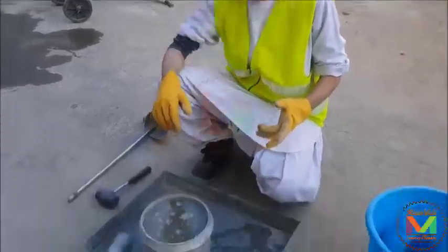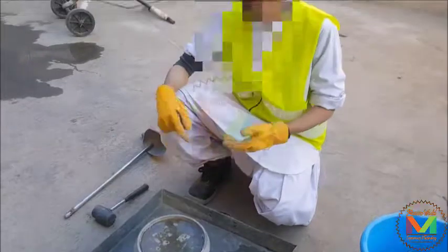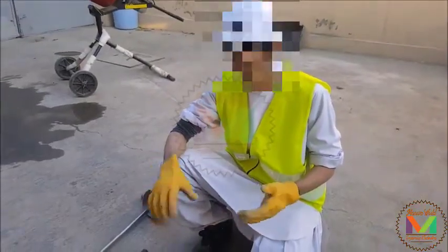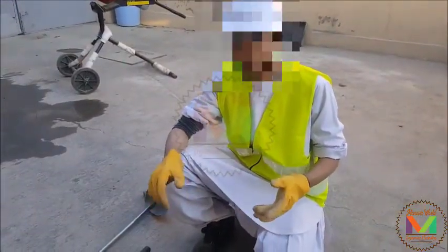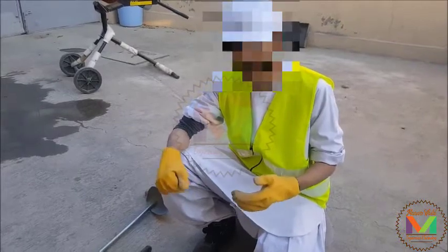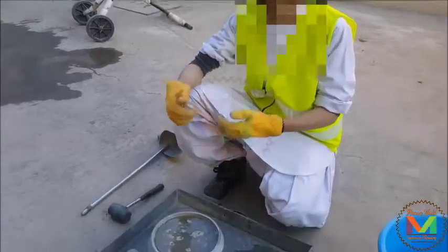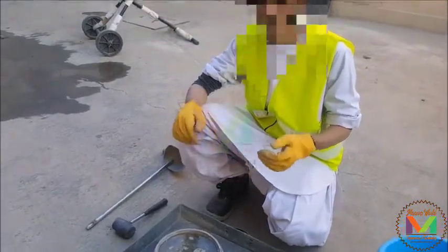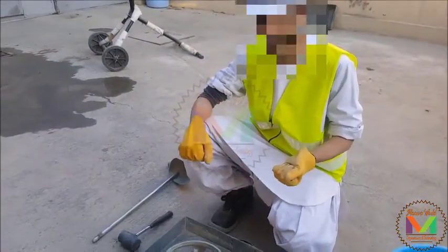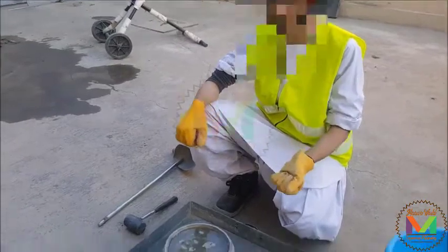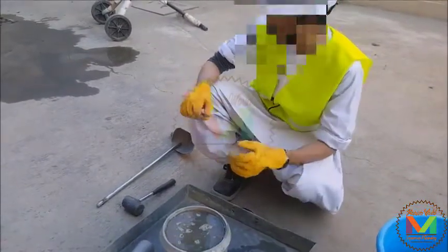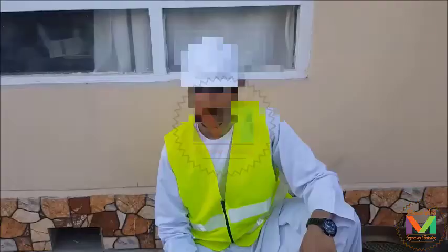As you can see, when all of the aggregate has been placed in the measuring bowl, we are removing excess from the cap, and the aggregate is inundated for a period of time approximately equal to the time between introduction of water into the mixer and the time of performing the test for air content, before proceeding with the determination as directed in 6.4.2.